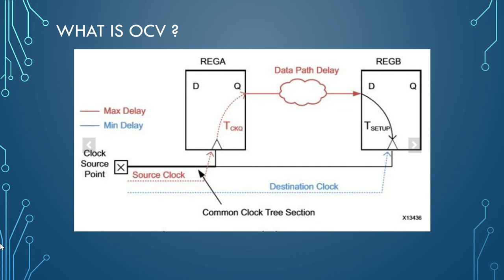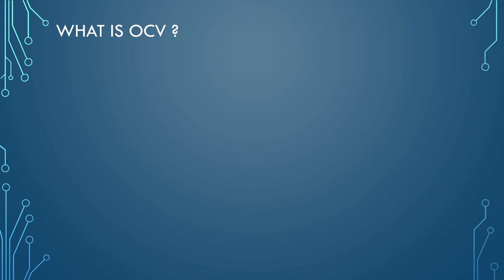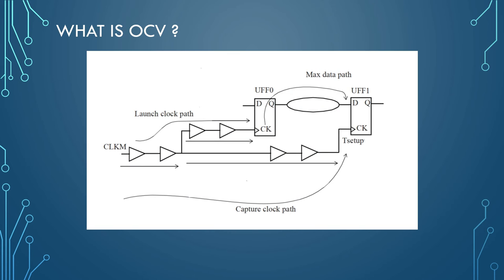The OCV effect is typically more pronounced on the clock path as it travels longer distances in the chip. One way to account for the local PVT variations is to incorporate the OCV analysis during the STA. Since clock and data paths can be affected differently by the OCV, timing verification can model the OCV effect by making the PVT condition for launch and capture paths slightly different. The STA can include the OCV effect by derating the delays of specific paths.